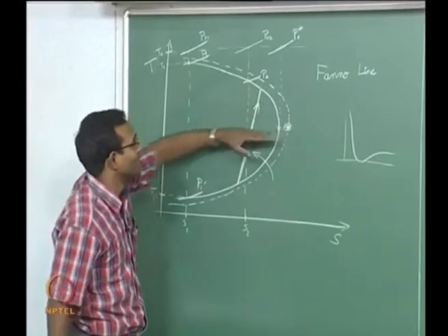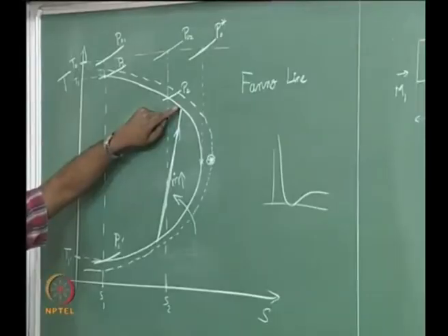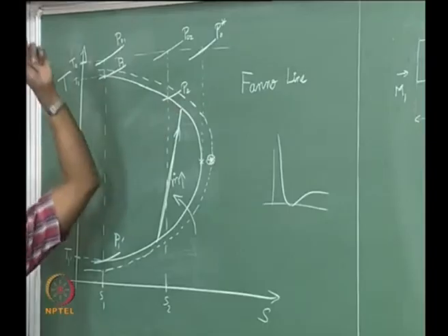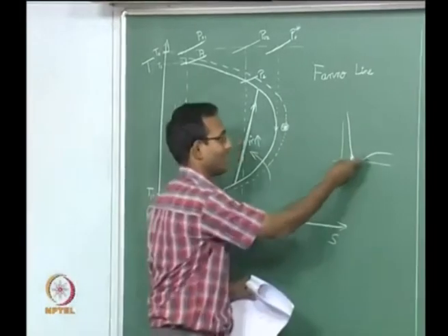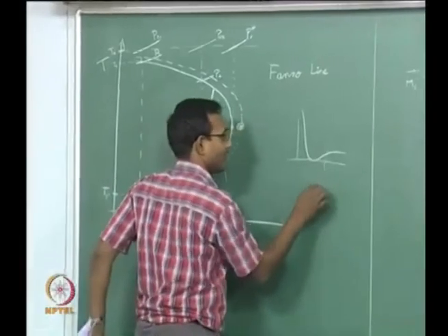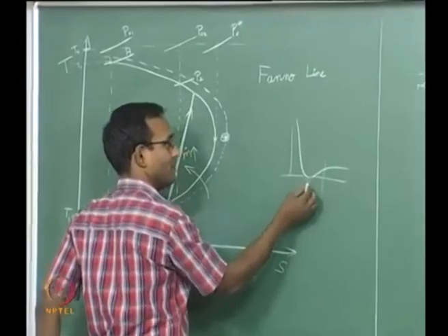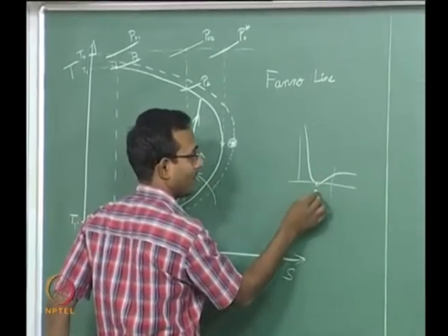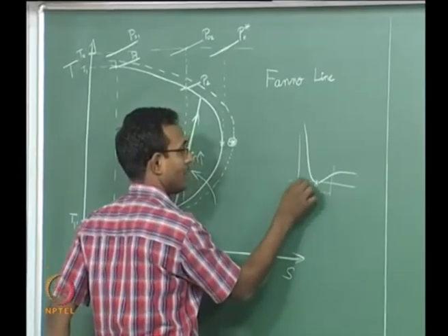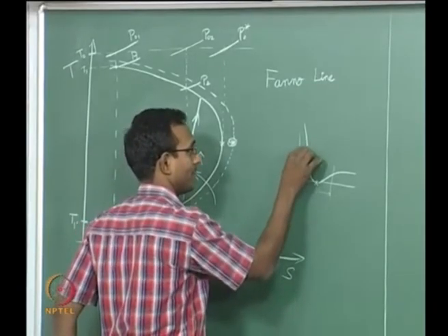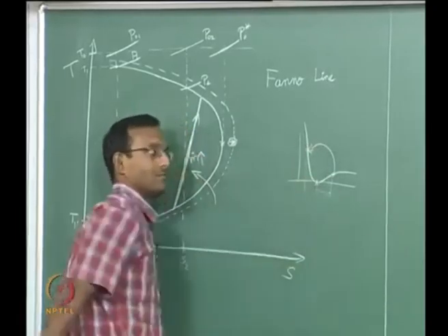We know that above this line it is a subsonic solution, right. It is a subsonic solution there, and when it is a subsonic solution, suddenly my L star is very high for the same F and DH. I have this curve here. So, say I chose this particular Mach number and from here it jumped to some other very low Mach number. This is M equal to 1, this is my supersonic limit. So, it is going to go very subsonic, it is going to be somewhere sitting there. From here it chose to go there.